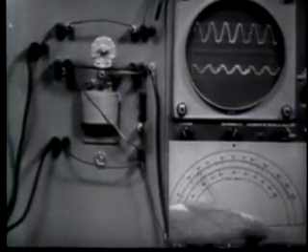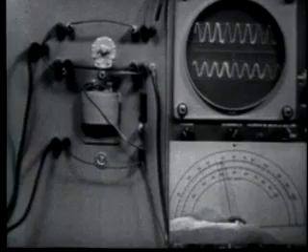The parallel tank in the shunt position is causing this circuit to function as a band pass filter. These frequencies below resonance are being rejected. There's not enough output there to operate the load device. But frequencies right around resonance are being passed. We have about the same output as we have on the input. So these frequencies are being passed. Now, these frequencies above resonance, however, are also being rejected. So we have a band pass filter.